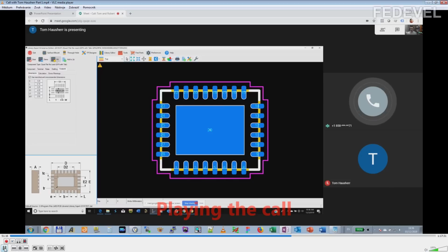Because if I create this pattern, they might create a board with 50 different patterns on it, and then populate the same package on these 50 different patterns, all designed by their internal engineering team. These component manufacturers have component engineers testing land patterns, and each engineer will come up with a different pattern, maybe two or three. They put all these patterns on a circuit board, manufacture and assemble the board, and then take that board through thermocycling, hot for 5 minutes and then cold for 10 minutes, then vibrate it, maybe put some G-forces on it, and then the parts will stop popping off the boards.